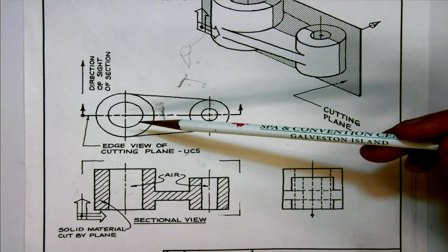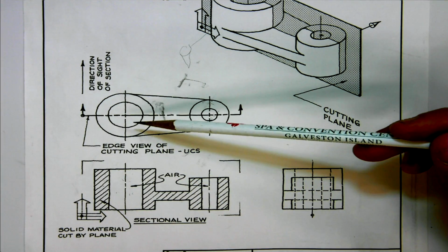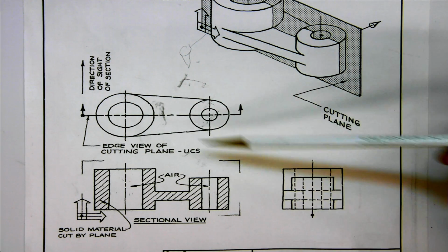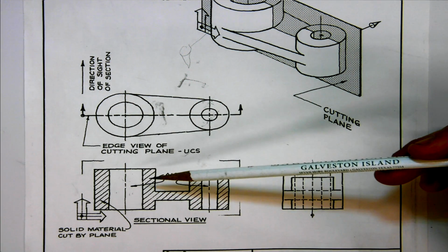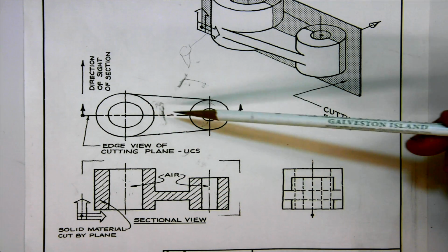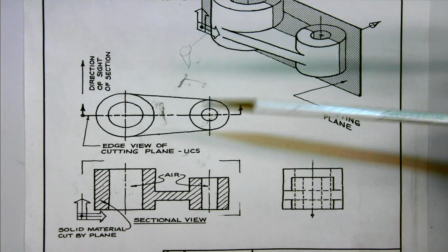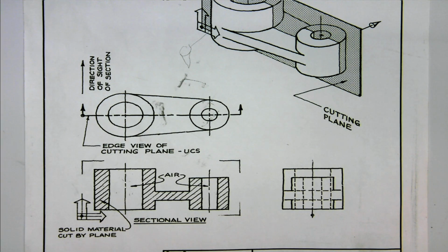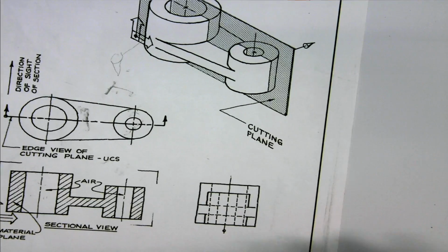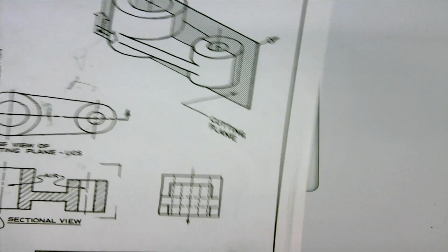Notice in these assignments you only have one section view and maybe either one or two other views. You will not create a front view and an additional section view. So again, the object here is cut completely in half. That's the theory behind the section views. Now, referring to some of your book readings, there are different types of things you need to know about section views.